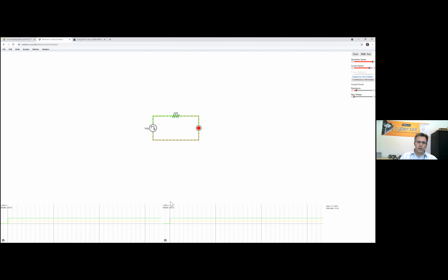So like there's 1.5 volts between the resistor and the LED, and then over here it goes from... it even shows, if you can see right here, it shows the current. There's the voltage, and then I swear I saw that. There we go. There's the current. There's a current trace, so 6.8 milliamps right there. And then there's also a voltage trace.